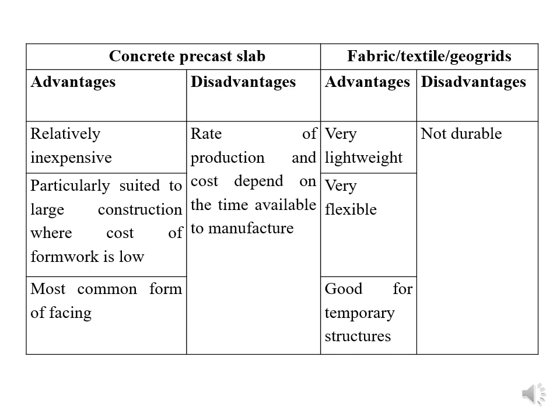Suppose you want to start construction of the facing unit tomorrow, and today you are getting orders. In that case, this will be a disadvantage, because you have to go for the precast. It will take time for curing also. So this is a disadvantage.